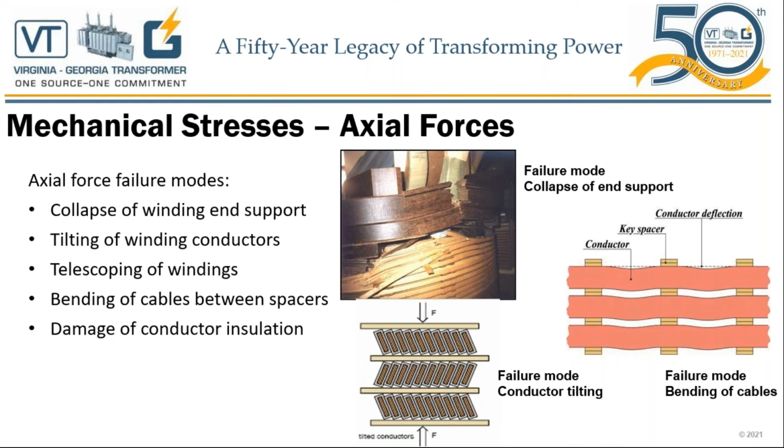Axial force failure mode. What are the axial force failure modes? Collapsing of the winding end supports. So look at the middle picture, and right above the conductors, you see what we call pressure rings, or some companies may call them winding tables.